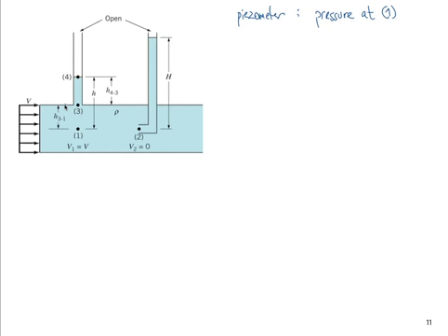So how do we do this with the manometer problem? If you recall the manometer problem, same fluid, same elevation is same pressure, but here we're changing elevation if we go from 1 to 4. So from 1 to 3, pressure at 1 is equal to the pressure at 3 plus gamma times the H between 1 and 3, which I called H31 here.